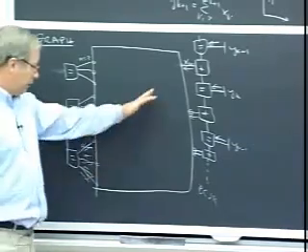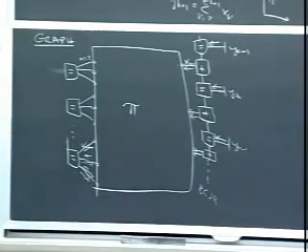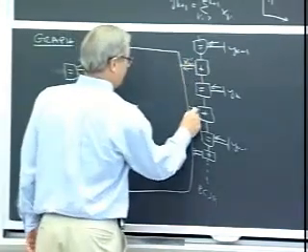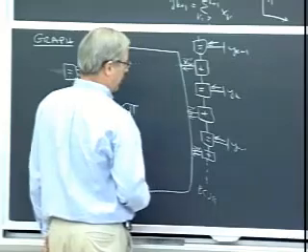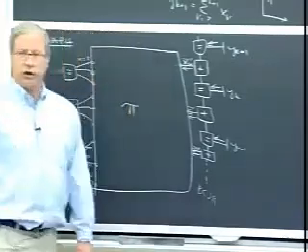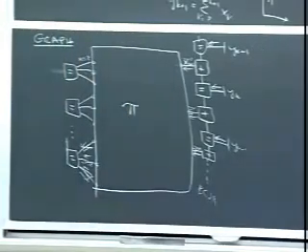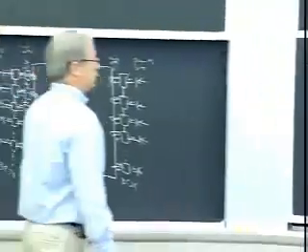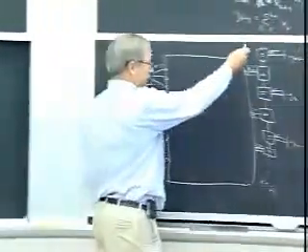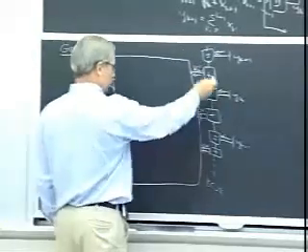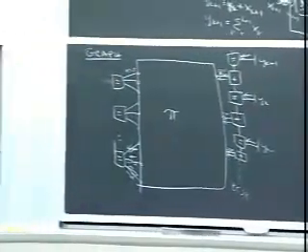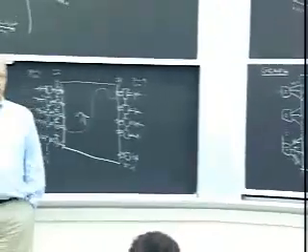So we combine and repropagate all these messages, and that gives us new information over here. And now, based on that, we can do BCJR again. So again, it's this left-right sort of alternation, one side, other side, which eventually spreads out the data through the whole block.